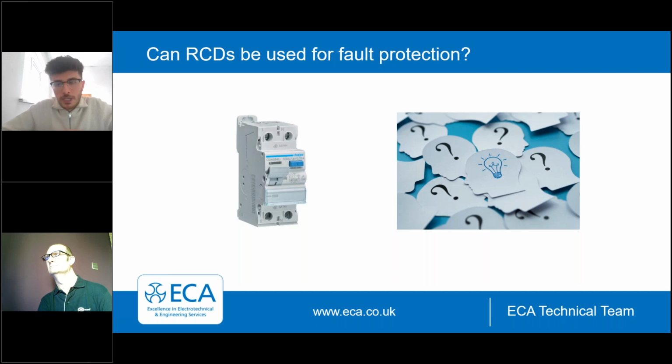If the method of fault protection is via an overcurrent device, then you should be looking to confirm that the impedance value is below that. If your impedance value is high, it may signify a fault. It may be that you've got a loose connection, so it needs consideration on why it is high, i.e. a TT system and so on.